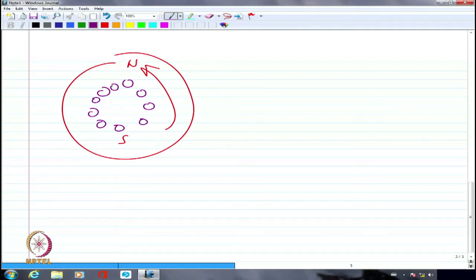So I'm going to have a rotor current because of the induction. That rotor current, the three-phase currents flowing through the conductors in the space distributed winding of the rotor, will cause another revolving field to be set up. That revolving field will try to interact with the stator created magnetic field, and that is going to produce a torque in the process of aligning with each other. That torque essentially will oppose whatever is the root cause for the torque production.